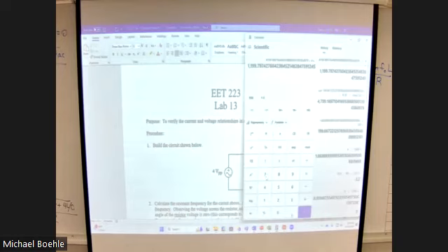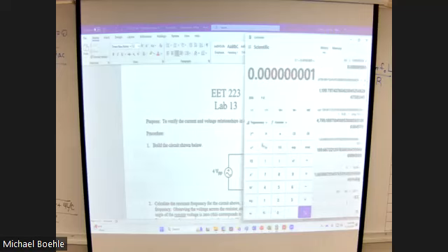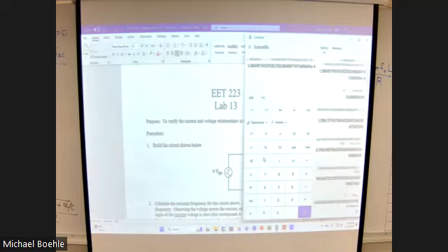So we're going to have 0.1 henries times 0.01 microfarads. You take the square root of that, multiply by 2, multiply by pi, and then take the inverse, right around 5,000 hertz. So if you build a circuit and you find a resonant point and you're not close to that, something's wrong. Okay. I like to give you that information so you know what to expect.